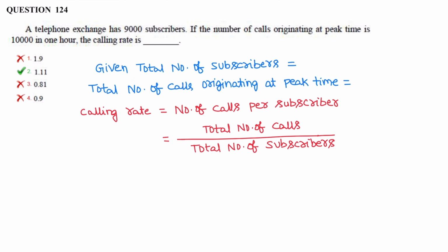Similarly, for a good conductor where sigma by omega epsilon is far greater than 1, the intrinsic impedance is given as under root omega mu by sigma at an angle of 45 degrees. Similarly, for free space, sigma is 0, conductivity is 0, and the intrinsic impedance is given as eta is equal to eta naught under root mu naught by epsilon naught, that is, its value is 120 pi, that is 377 ohms.